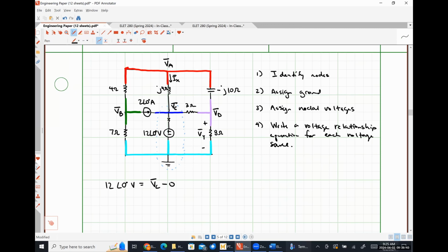Realistically, we would actually have another node there that would have its own nodal voltage and all of that kind of good stuff. Yep. So anywhere there's a point of interconnection between 2 or more circuit elements, there's a node. So we have to identify every single one of them. Those are very easy to overlook, but they're still a node because they still represent a point of interconnection between circuit elements.